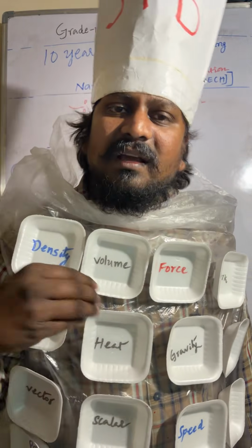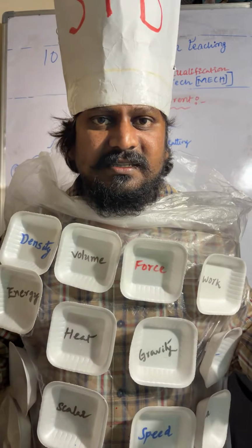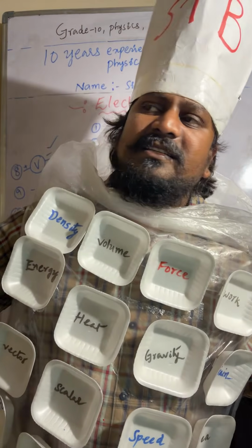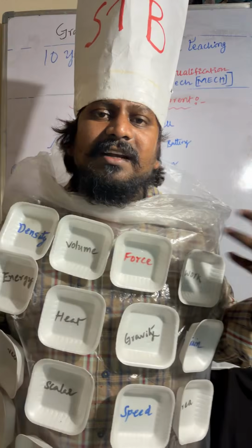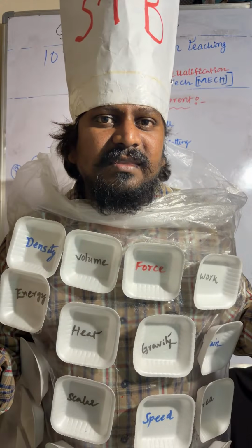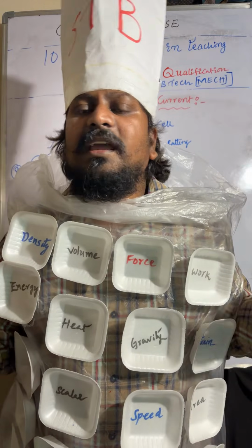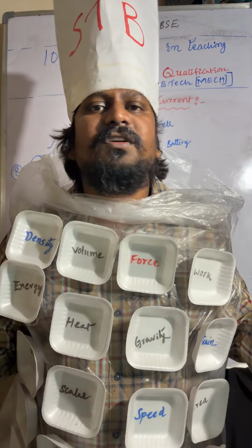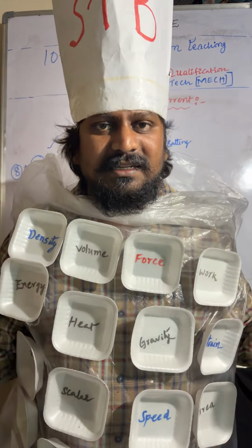So what if the voltmeter is connected in series? Generally a voltmeter measures the difference in electrical pressure, right? In one place it is high pressure, in another place it will be low pressure, and it measures the difference. In series combination, throughout the path the current is the same. So where and how will it be measured? Even if you connect it in series combination, the voltmeter cannot show a reading, because there must be some difference in electrical pressure. Only then will it measure the difference, right?